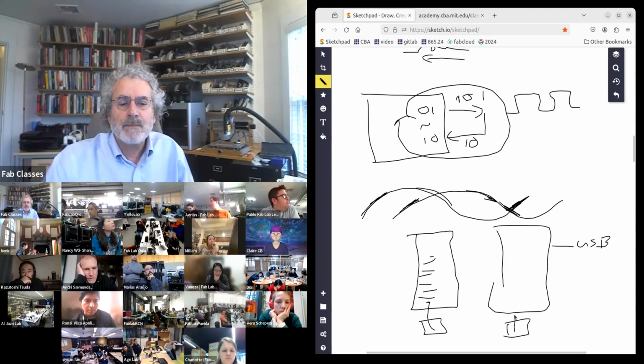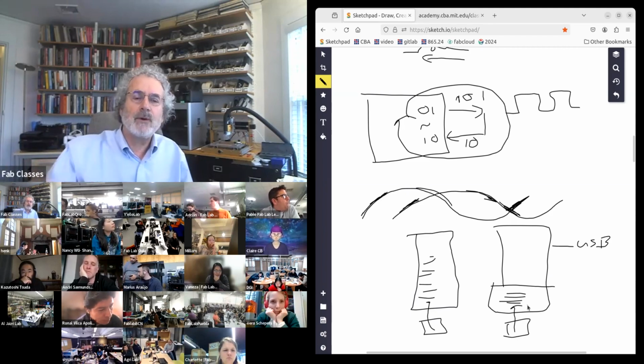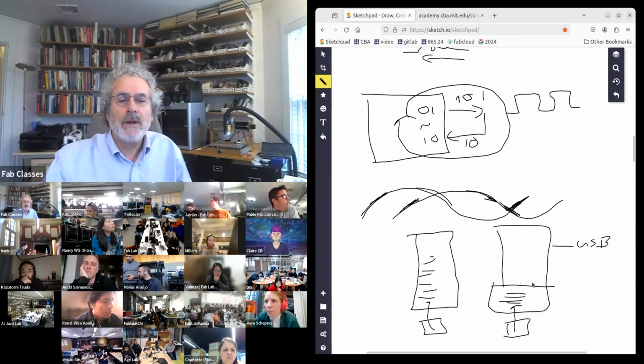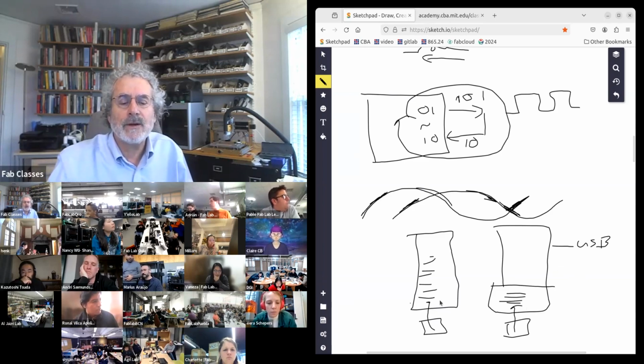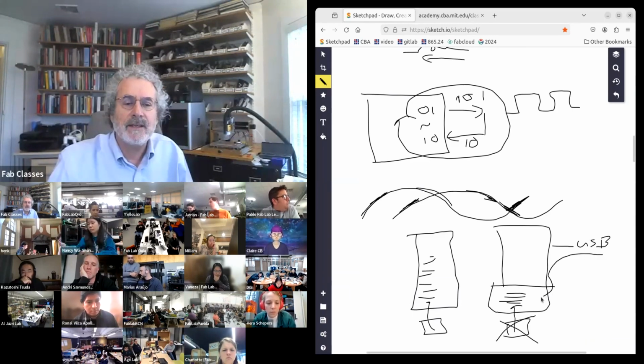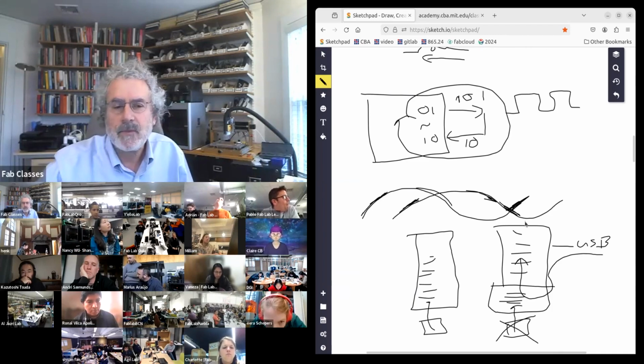There's a very special program you can load that stays in a certain part of the memory called a bootloader. And that's a program to load programs. So once you load the bootloader, then you no longer need the programmer, because what the bootloader knows how to do is listen to the USB and, over the communication port, load a program.